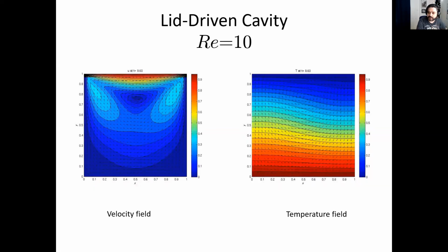Now, what have you seen here? The speed of the video is exactly the same as on the previous one for Reynolds 100. But what you have seen is that the adaptation was extremely quick. The reason for that is that the Reynolds number is lower, so your viscous time scale has become much smaller.